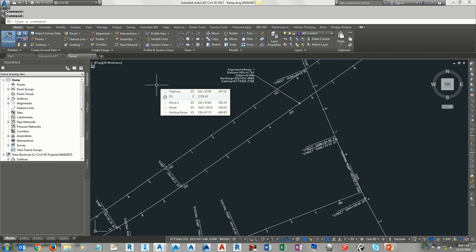So if you're using it, that alignment, it's just that Civil 3D will not do calculations. You know what happens, right? Civil 3D when it starts thinking. Anybody been through this? No? Okay, so it can happen to you, and it'll go into a loop where it's not getting the material calculation. So the trick was to have one alignment created about 0.01 feet to the left, and it will divide left and right, and you get two tables of material quantities, pavement structure, earthworks, whatever you want.